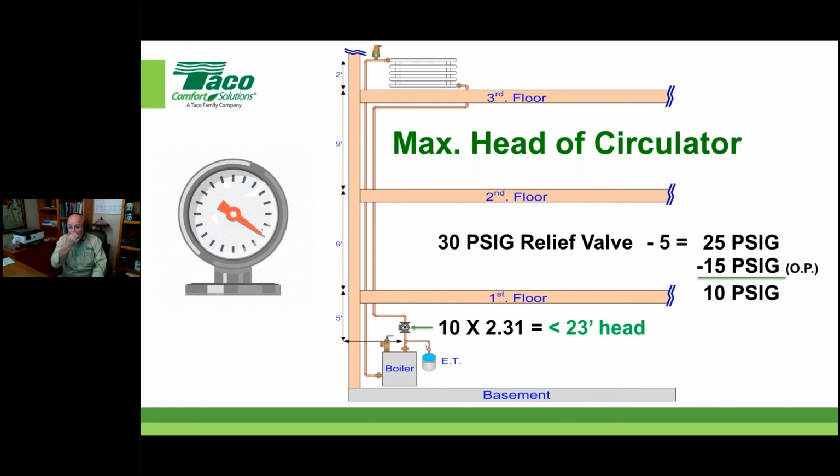Could you please further explain why the 4 to 5 pounds additional pressure for the air vent? Sure. If we were just sitting here at, like, 0 psi or maybe only 1, we're not going to do as good a job of getting bubbles of air to come up out of this air vent. If I get a little higher pressure, that 4 or 5 additional psi, we just want that at the top. It does two things for us.